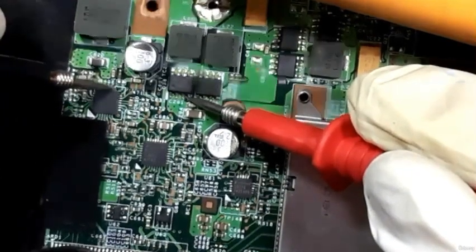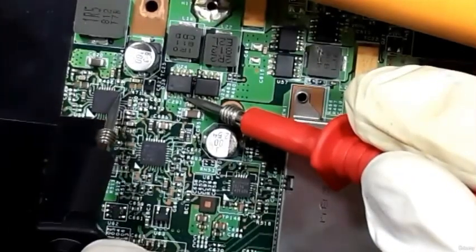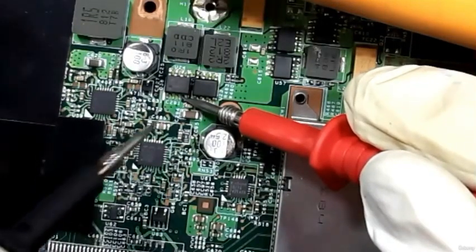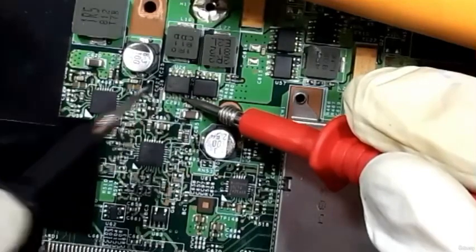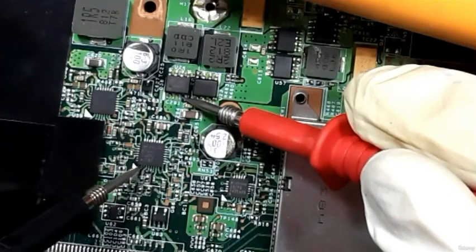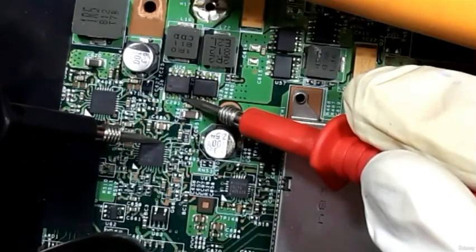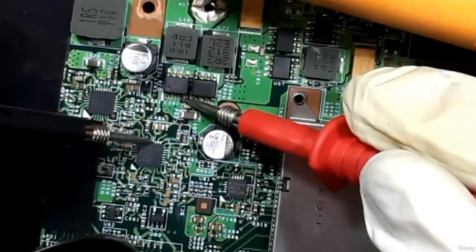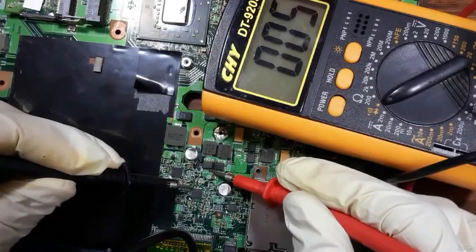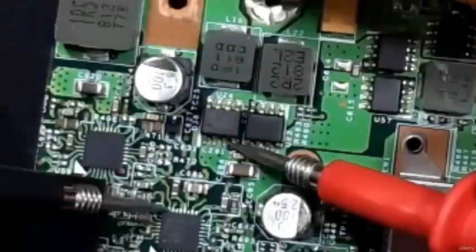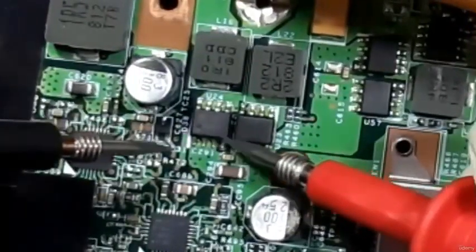You should hear a buzzer, a continuity. Okay, let's check this. Okay, let's check this also. Remember, this probe is on the gate of this MOSFET. So let's check this. Now buzzer. Let's check this side. Okay. As you see in the multimeter, this pin here is connected directly to this gate.